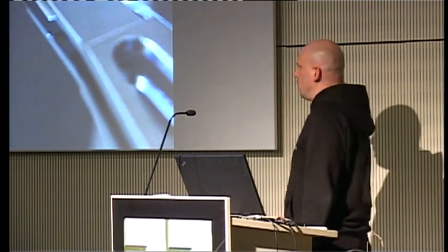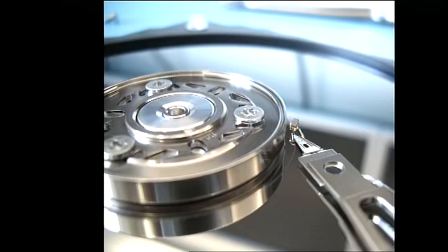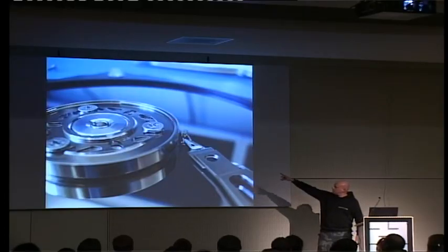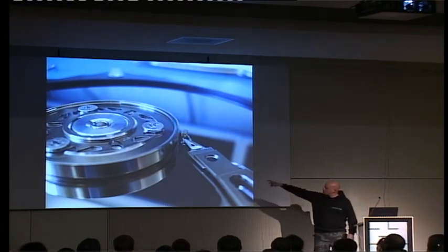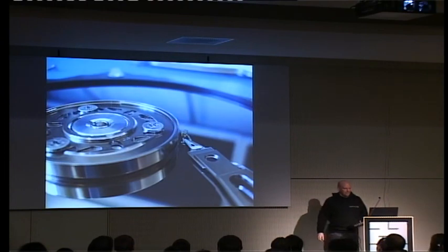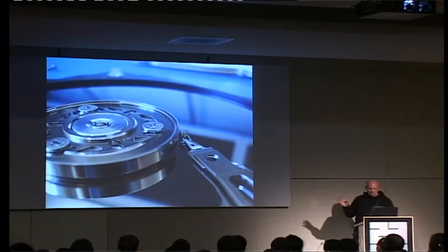I told something before about stiction. Now, if somebody tries to turn the platter with the heads glued to the surface, stuck to the surface, then it will look like that afterwards, because the head will still stay on the surface, and if you apply a rotating force, it flips up the head. And in this case, I don't know if you can see it, the spring from the heads went down to the surface and did a scratch there. So if the drive is stuck, don't turn it.